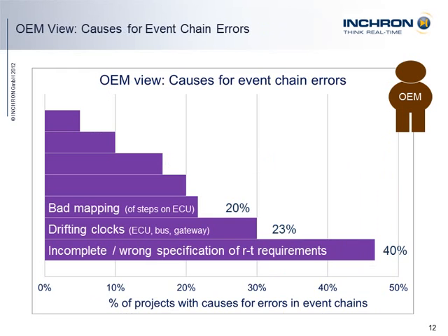What in detail is included in the 250 millisecond requirement from the OEM for the event chain? The asynchronous sensor as well? Until the CAN task send was activated? Until the message was written into the send register? Or until the last bit of the message was on the bus? Until now, the developers couldn't observe the dynamic behavior of event chains. So why should they define it in detail?